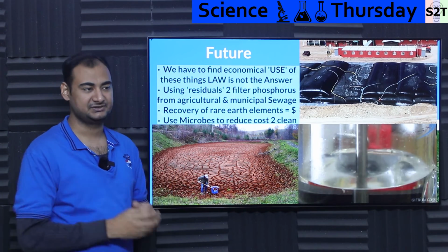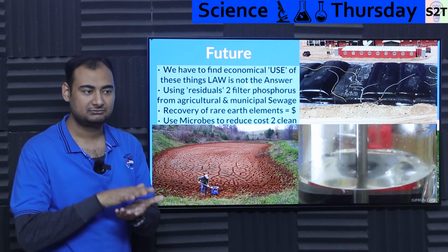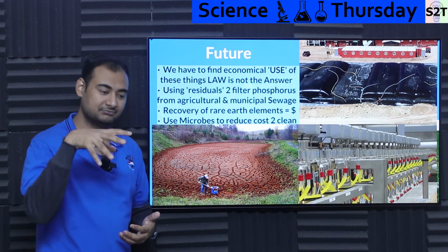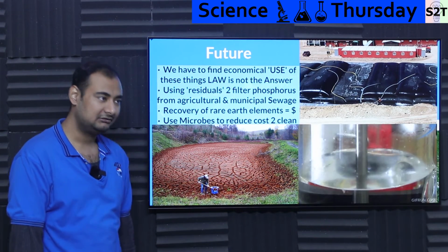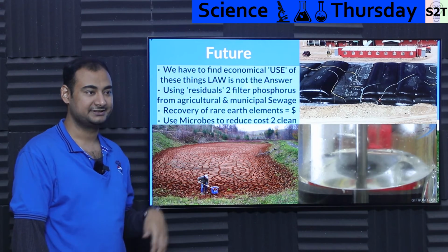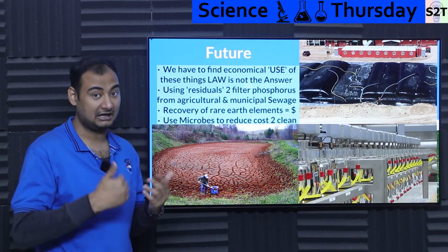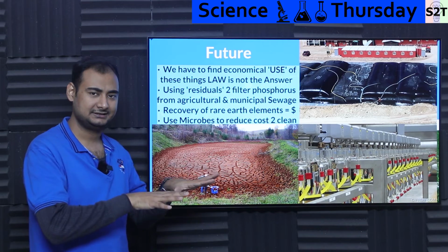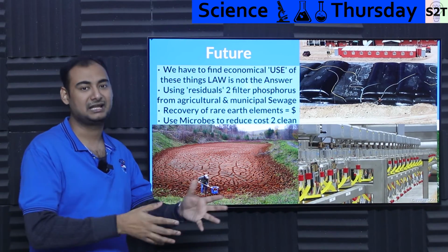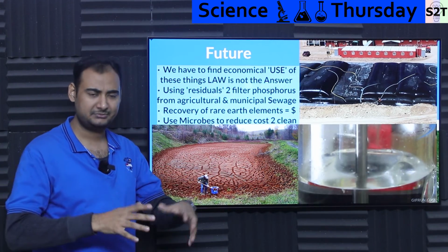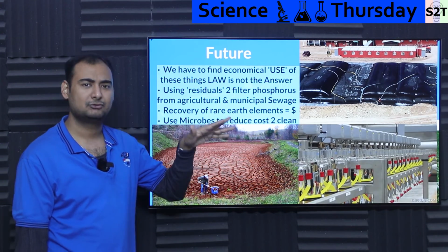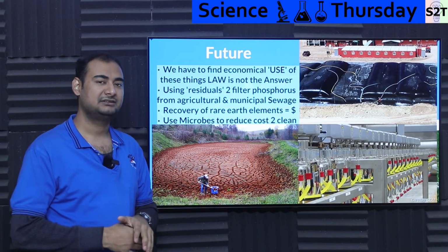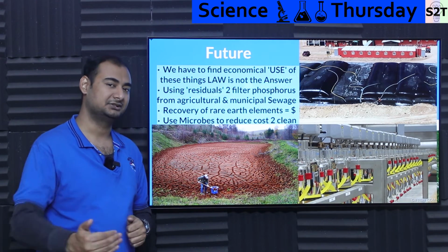What does taming it mean? Basically, you take the AMD and you throttle it even a little bit. Nature can put a foothold. The moment nature puts a foothold, it can break it down. It's like, bro, I got this. All we have to do is basically chill it a little bit. Instead of trying to solve all the issues ourselves, let's tame it a bit. Of course, consume lime on it, tame it a bit, aerate it a bit. Let's say the pH level is 2. Let's bring it to, let's say, 4.5. At that point, microbial life that is acidic in nature is like, I got you, fam.